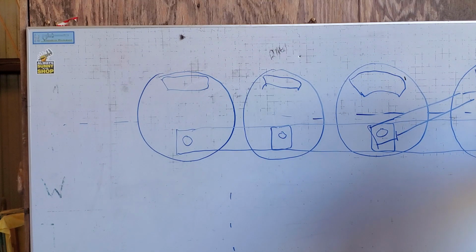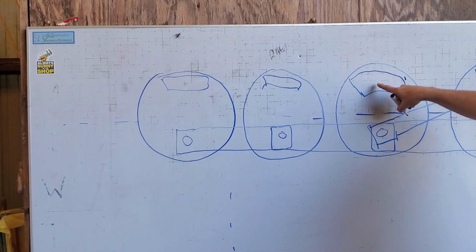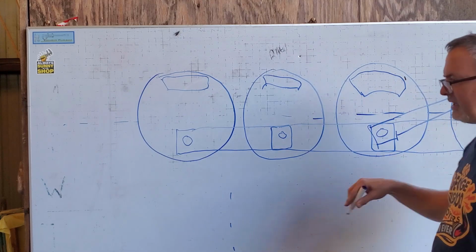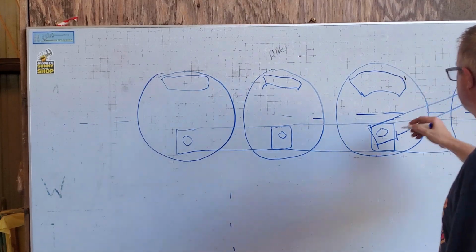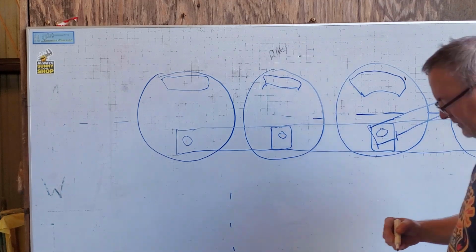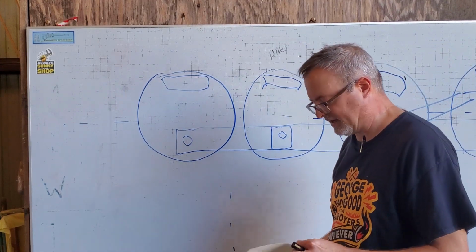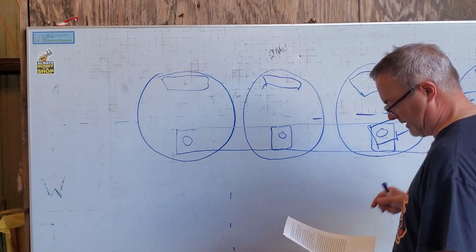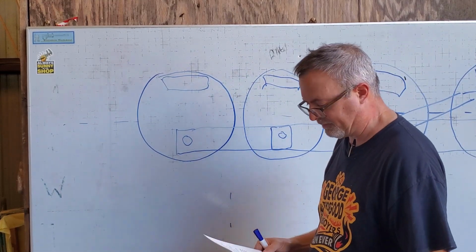But once again, this is a trade-off because they're trying to balance the vertical force that this side rod is putting into the rails. But then these counterbalances are always opposing the motion of the side rod, so they tend to completely cancel things out. You still have to do the horizontal motion of the piston, crosshead, and connecting rod, but those are all to balance this massive member here, and that's only on locomotives.